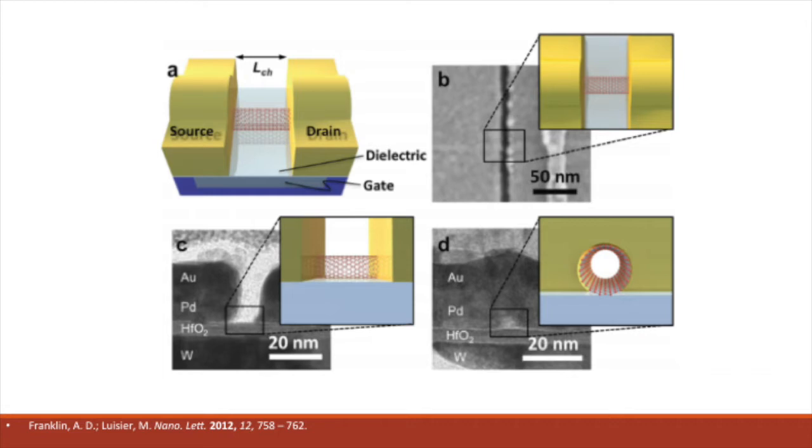Their sub-10 nanometer transistor achieved a diameter normalized current density of 2.41 milliamps per micrometer at a low incident voltage of 0.5 volts, which was nearly 4 times as great as what the best competing silicon-based transistors were capable of offering. Franklin's sub-10 nanometer carbon nanotube transistors opened the door to numerous areas of further research, and it was not long before these transistors were applied to even more complex circuits and applications.